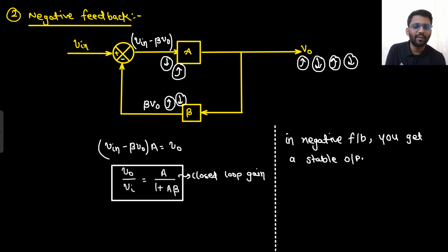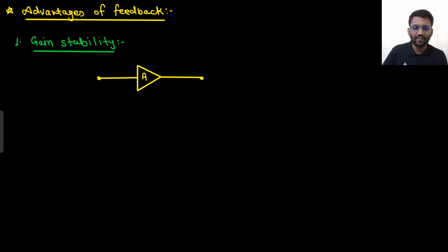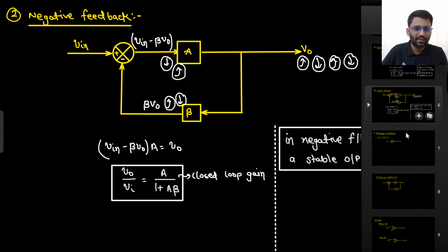So what is the way of determining a negative feedback? Whenever you see a circuit, you will first try to increase the output. Then you walk around the loop, and if you see the output is getting decreased, that means it is working in negative feedback. Otherwise it is working in positive feedback. Let's see an example of an op-amp. Very easy example and it is highly used.